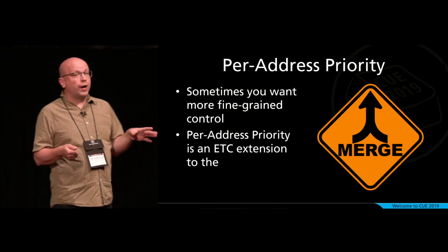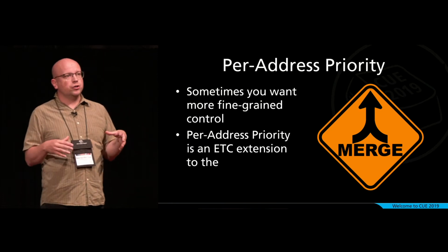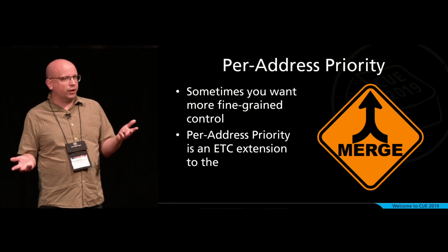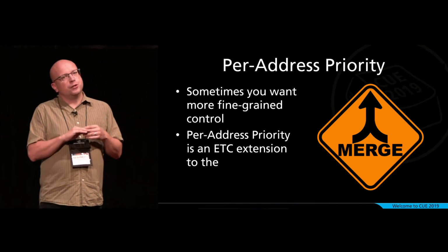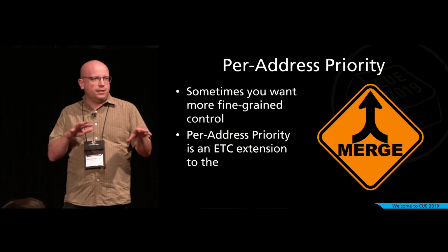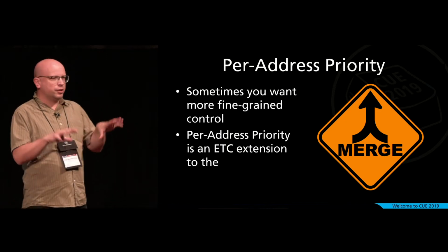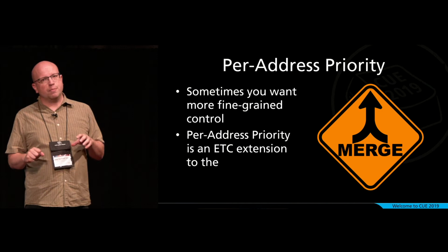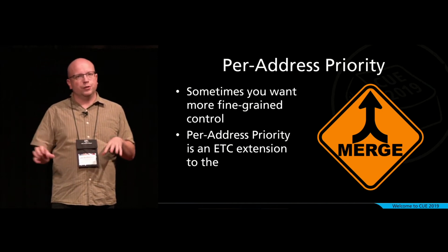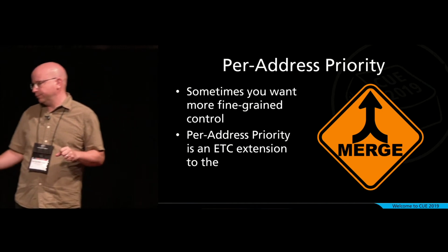So something to be aware of is that this is an ETC extension to the standard. We have told other manufacturers about it, but not many other people have implemented it. So if you're mixing ETC gear with other people's gear and you're seeing some strange effects within a universe, that's something to look out for. It might be related to mixing per universe and per address properties.